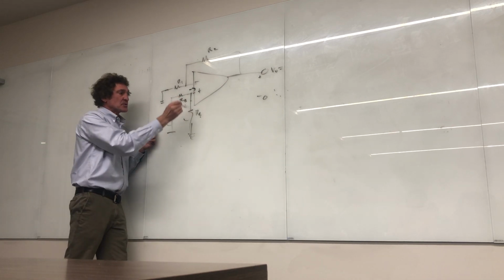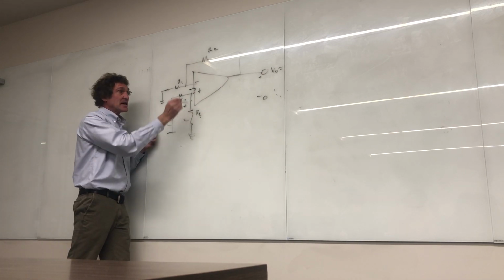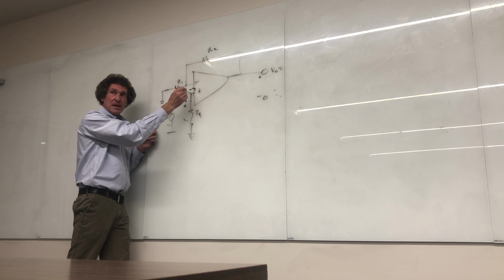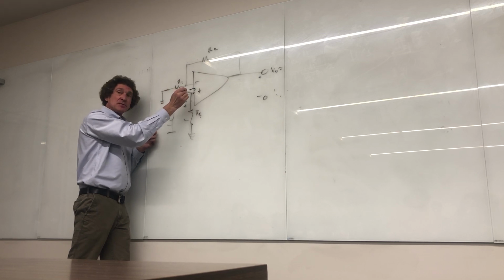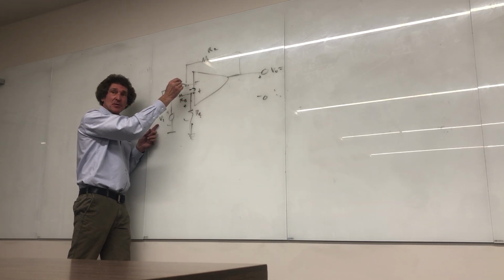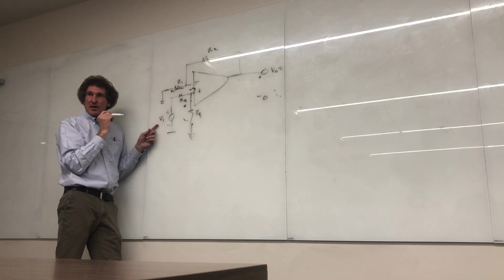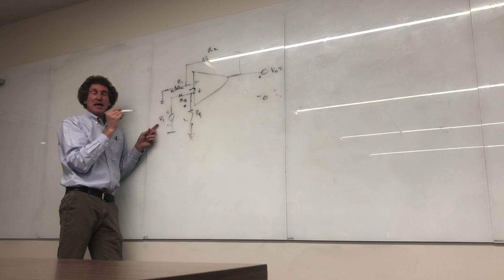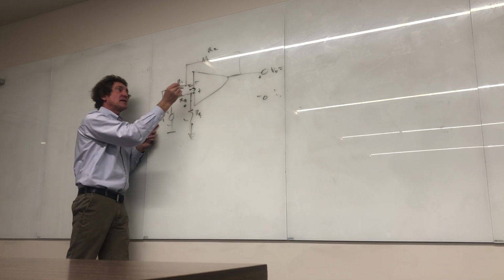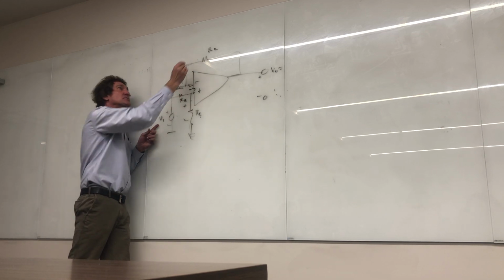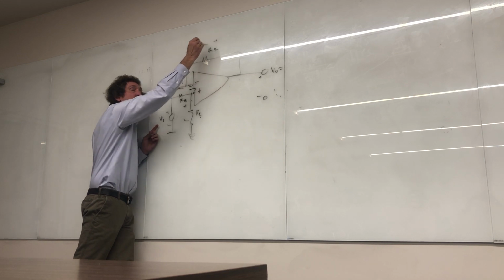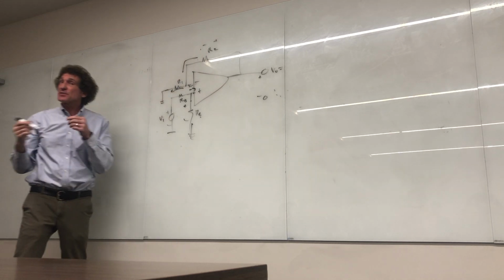So if I can get the voltage across this, which is simple voltage division, I've got the voltage on the plus terminal, right? If I've got the voltage on the plus terminal, I have the voltage on the minus terminal, right? Once I have the voltage here, I have the current through there, don't I? See the process? If I have the current there, how much flows out of there? None. Where's it coming from here? Don't I have the voltage here now? Yeah, so that's the thought process.